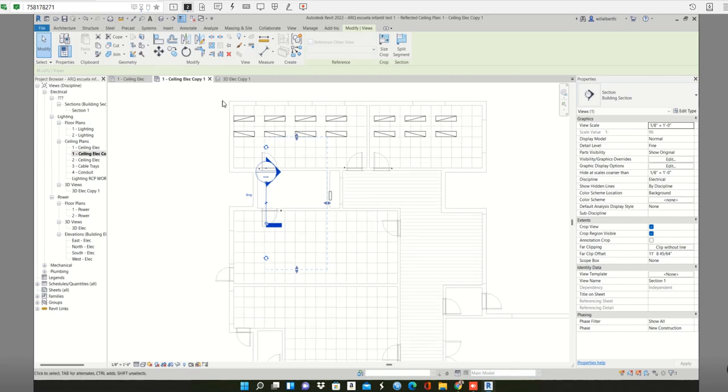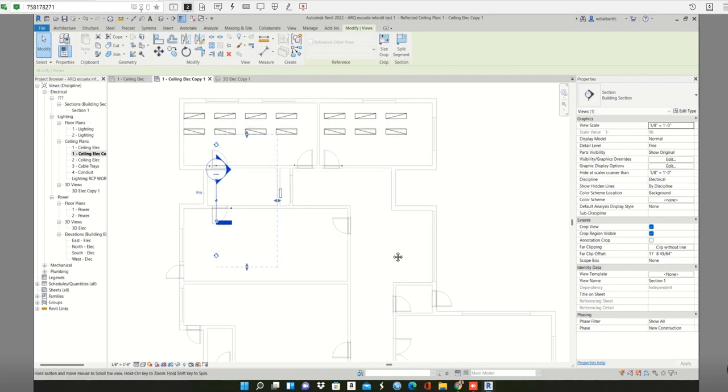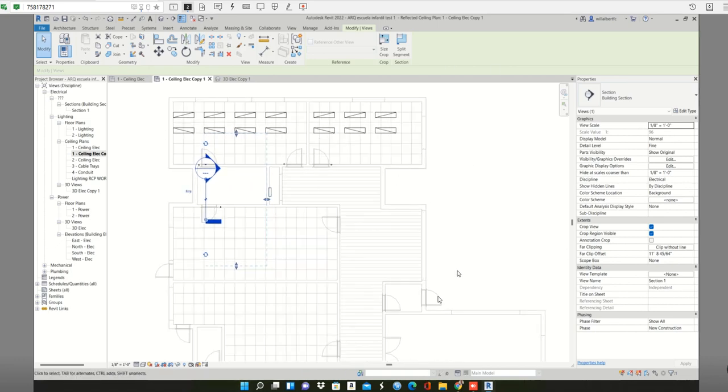I would like to make the following thing. This is a good practice because you will get the idea of how integrated Revit is, and we will also see the schedules and the electrical schedules that are very important. I would recommend you download this file again, put the lighting features, and put the circuit first. Then model the conduits and the cable trays.